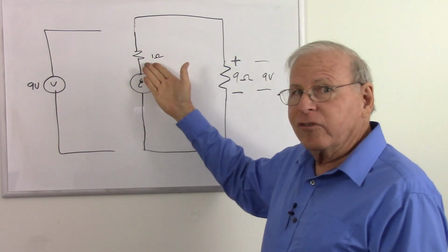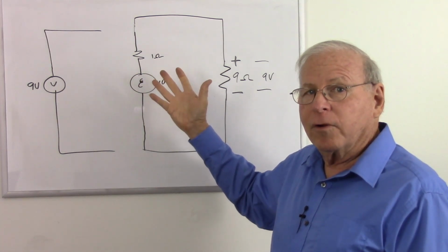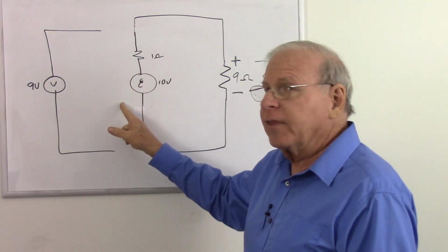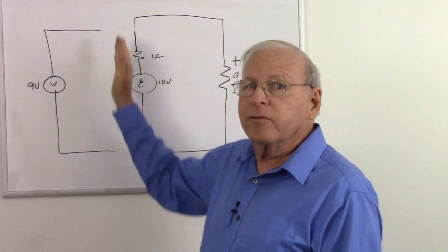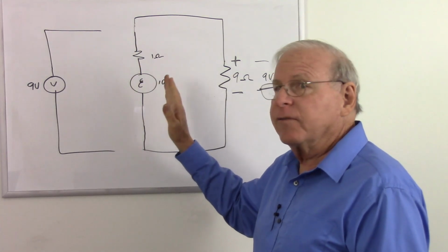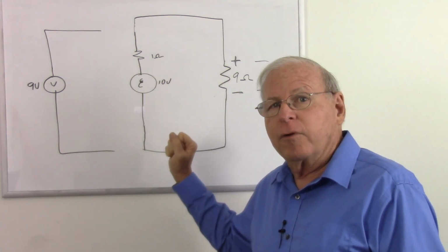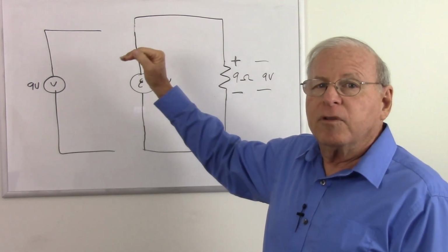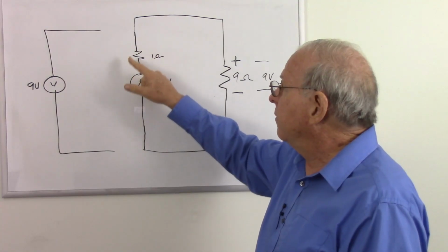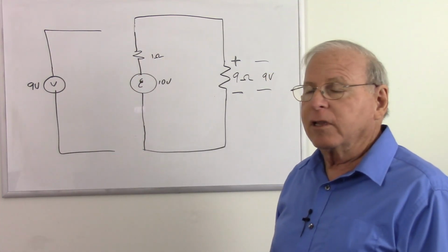So is this resistance in series, in parallel, both, or neither? Well, it depends on the way you look at it, but if we look at it in parallel, that didn't work because the electromotive force was pushing the current the other way. So it could be in parallel, but because of the nature of the circuit, having this electromotive force pushing, that path was blocked. Therefore, we have to find another way to model it, and we found that if we model it in series, it works perfectly well.